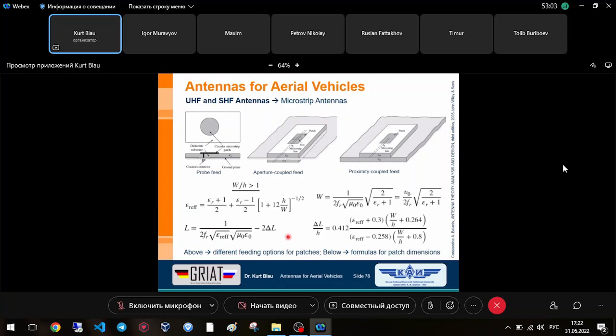It's clear that such a patch element, a single antenna, has very large dimensions. Let's say for 70 centimeters, the name says it's 70 centimeters square, and you can realize this also with air as substrate, which needs some holding elements from, for instance, dielectric material, or you can use foam as a substrate, like polystyrene foam.